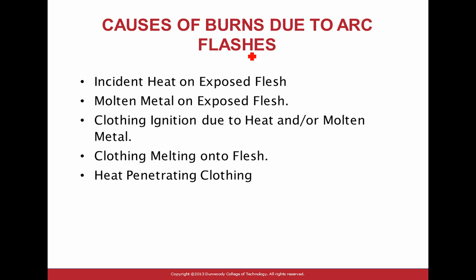Causes of burns due to arc. Here are a few things, guys. Incident energy on exposed flesh, you're done. That's why we dress you up. Molten metal on exposed flesh, also you're done. How about your clothing igniting? That's why they have the arc rated gear that you put on, so you don't catch fire yourself. Clothing melting onto the flesh, that's why you avoid nylon or anything that can melt.